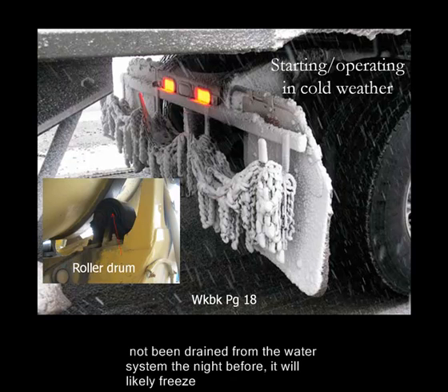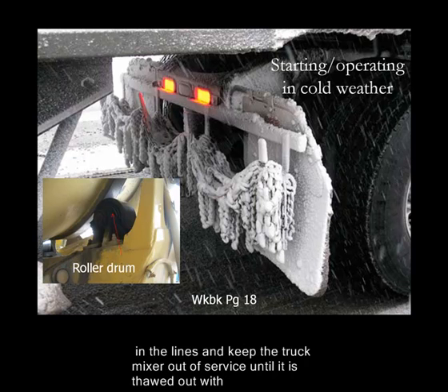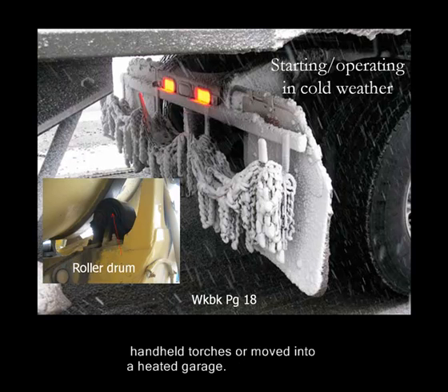If all the water has not been drained from the water system the night before, it will likely freeze in the lines and keep the truck mixer out of service until it is thawed out with handheld torches or moved to a heated garage.